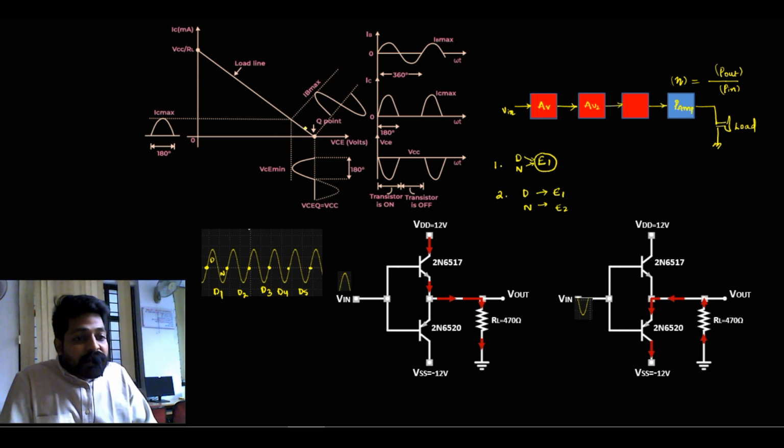The same way, whatever transistor I'm using, if it is to process the positive half cycle and negative half cycle, I have to make sure I provide the accommodation, meaning the transistor needs to be operated in the middle, so that the positive half cycle and negative half cycle are processed by one transistor. That's what happens in amplifiers, voltage amplifiers, common emitter kind of circuits.